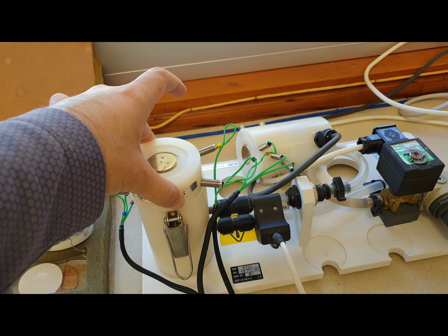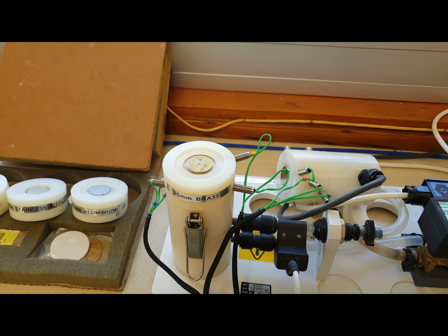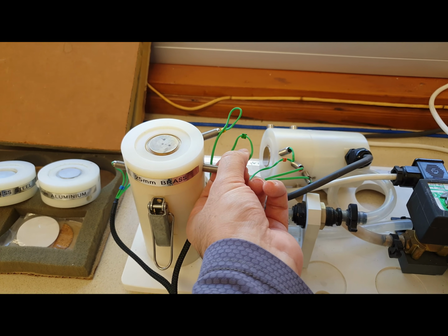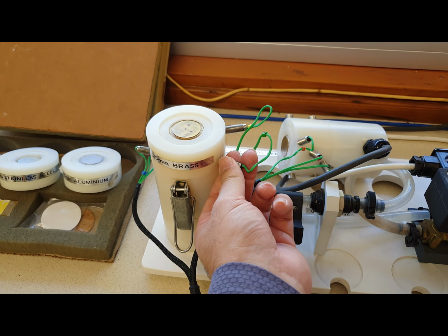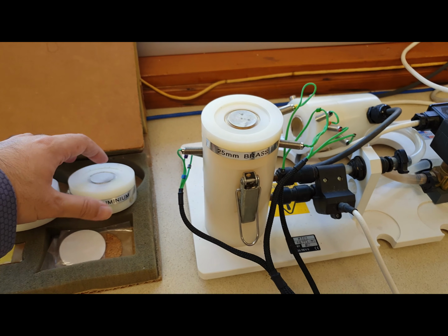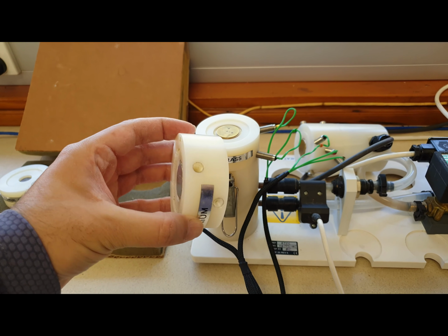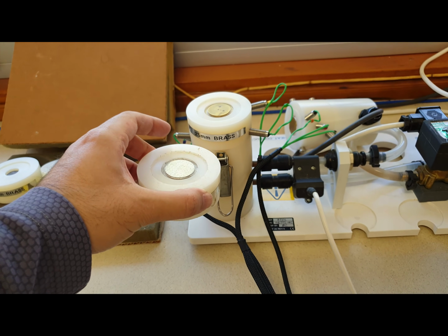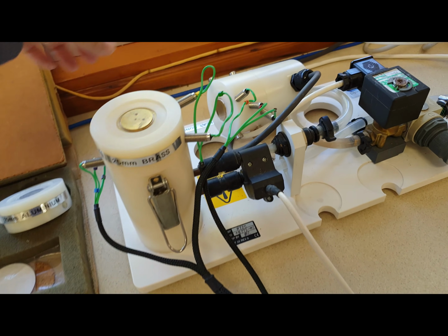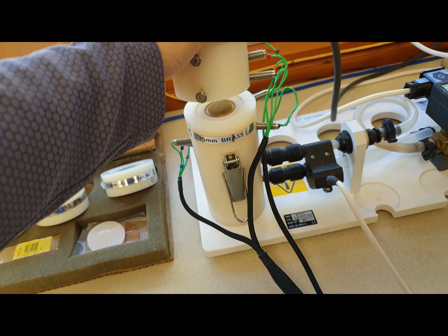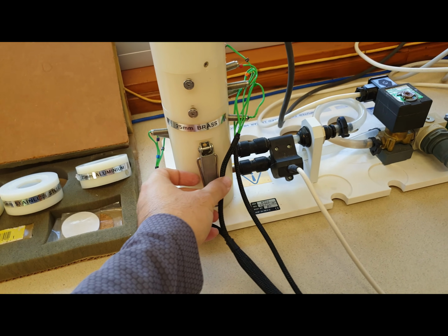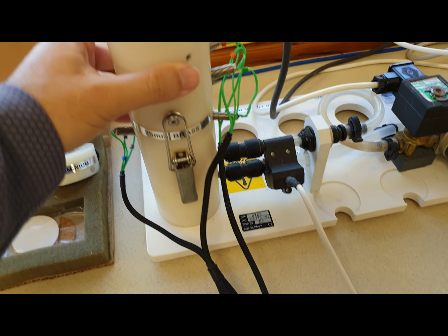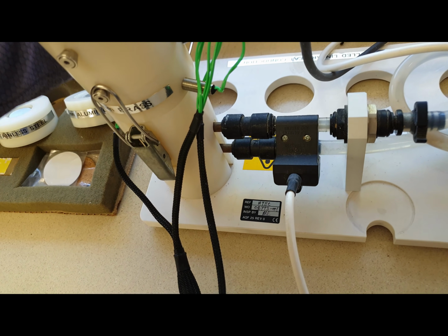If you want to open the thermocouples, you are just going to turn this screw, open the thermocouple and replace it with this. You can see we have two holes here to put those thermocouples in and replace with this one. So let's close the upper part, close the clamp. We need to do this for both sides.